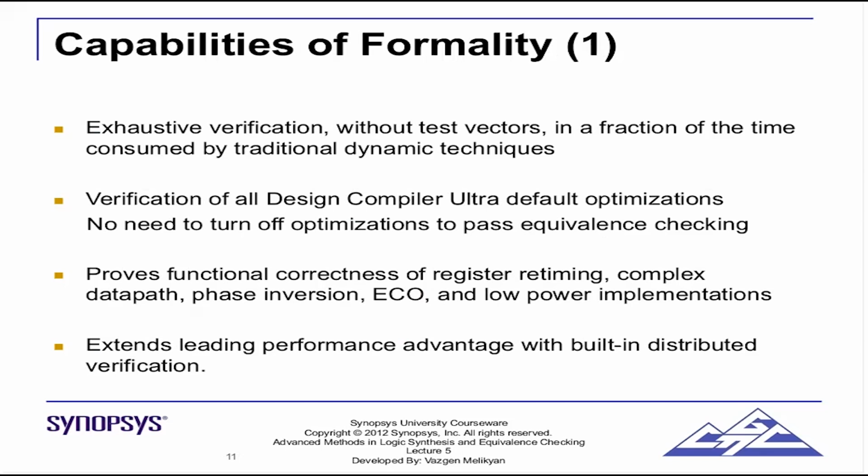So this is a very important thing here. Now what happens is that, as an engineer, let's say I am using a third party tool. I am using a tool which is not Formality, but I am using Design Compiler, the compile_ultra command. Now let's consider a case where I want to do retiming. What retiming does is it will move the flops around in the combinational logic cloud.